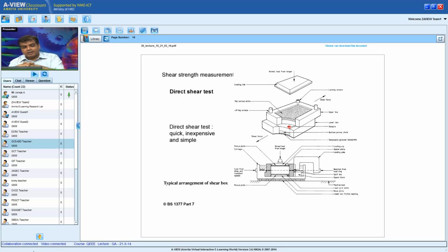Over here lies a very tricky question. We said to begin with there is no shear stress on this horizontal plane, because of which this horizontal plane was the principal plane. Now if shear stresses are generated, it is no longer a principal plane, meaning the vertical stress which I have applied is no longer the principal stress value.